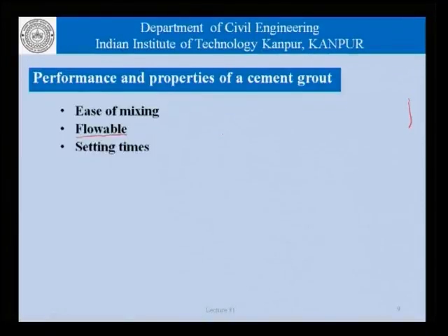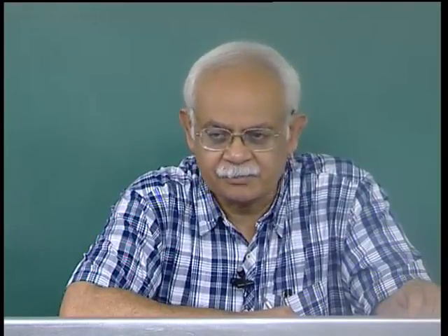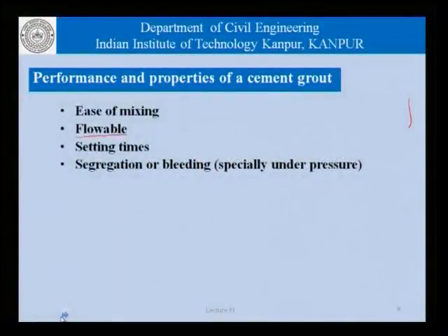Another property for the grout which would be of interest to us is the setting time. Like all concrete construction, the grout, once it has reached its final location, we would like the system to set, and therefore, the setting time is of great importance as far as grouts are concerned. Segregation or bleeding, especially under pressure.